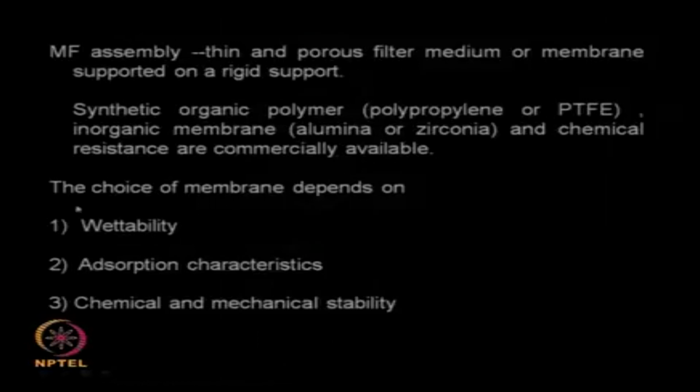The most important points we need to consider are wettability, because the membrane should not be very hydrophobic, otherwise wettability will be very poor. Absorption characteristics: will the membrane material absorb salts, because if it absorbs and starts swelling then that will be a problem.